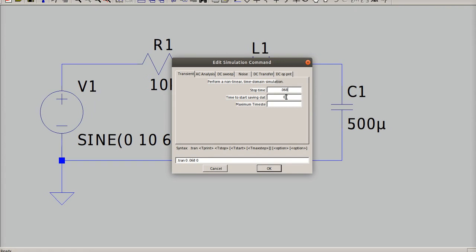And let's start after 1 cycle. So what I'm basically telling it to do is wait this amount of time before it starts showing me the waveform. That gives me some time for my transient to get out of the way. Start at 0 when you're starting out. But to get 3 cycles, the difference between my stop time and my start time has to be for 3 cycles. And my maximum time per step, that is my 1/10.